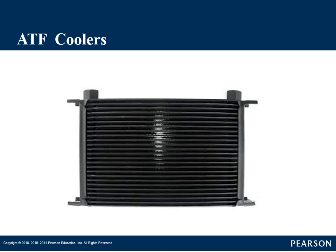The other thing about auxiliary coolers is they're rated for a certain size, for certain BTUs. You need to figure out how many BTUs of heat exchange you need, and that'll determine how big a cooler you want on your vehicle.